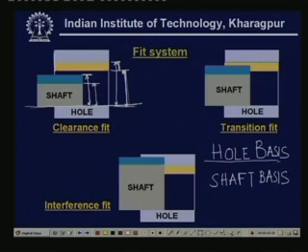What is the hole basis? That means we consider the dimension of the hole to be the reference over which we make the measurements, and shaft basis is the dimension of the shaft being the basis of the measurement. But normally it is very popular to use a hole basis. The reason is that, how do you make a hole? From the preliminary workshop practice, you know, just by using a drill you can make a hole.